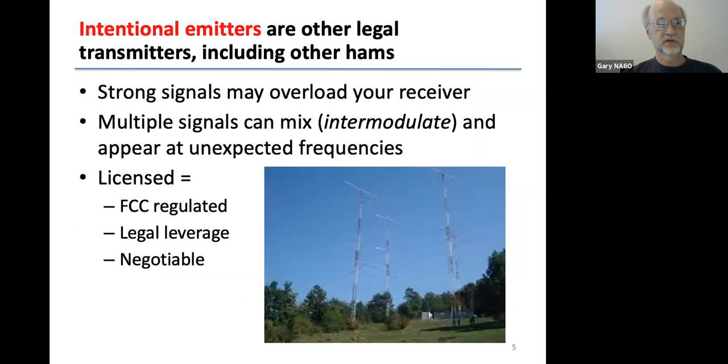So then there's intentional emitters. Okay, this is other legal transmitters, things that are intending to generate signals of some kind. And one of the biggest issues here is a case where strong signals may overload your receiver. Anyone who's taken their little HT up on top of Mount Diablo or something like that, where there are many high-power transmitters in close proximity, may well overload your receiver. If there are multiple transmitters, they can mix. That's intermodulation, so they appear at frequencies you don't even expect. A classic thing that happens at Field Day: you get many transmitters on the air in an ad hoc configuration, and you start interfering with one another.